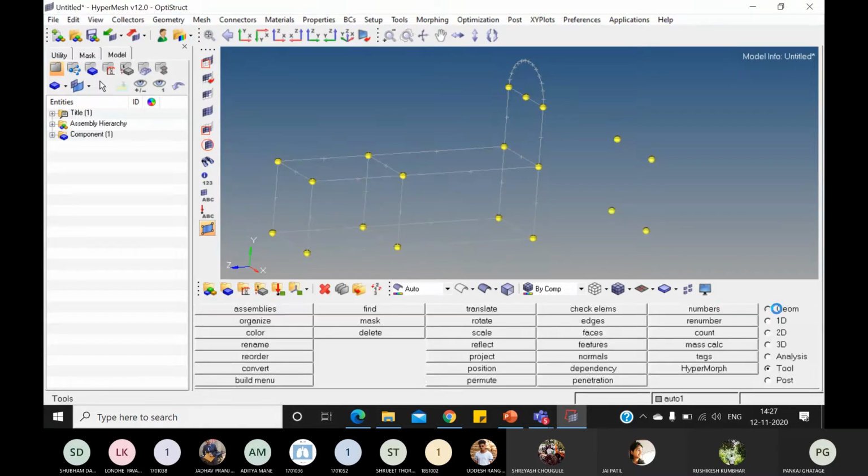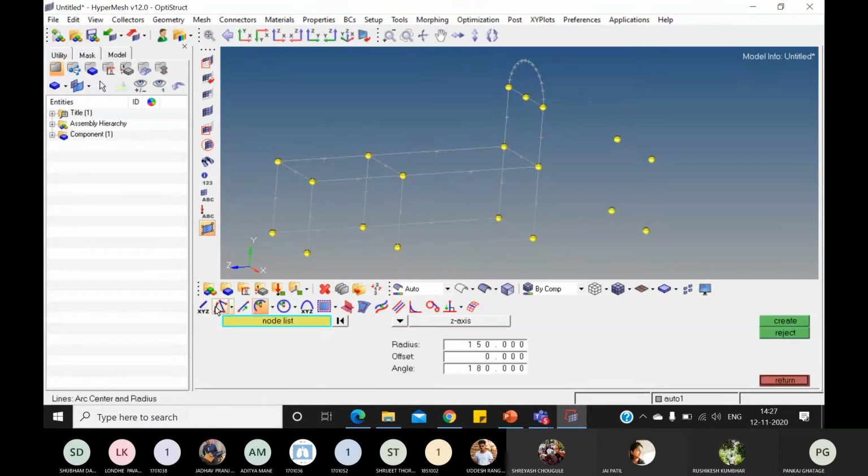Go to the geometry line, then select the line option and join it. While joining, join the front top surface first. Then slowly you have to close the loops. Do not join randomly. So this part is completed, and then finally you can complete the bottom part. Do not join this line first, then the second line like this. Do not do it like this.